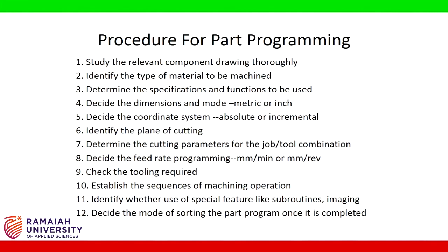Decide the feed rate programming, mm per minute or mm per revolution. Check the tooling required. Establish the sequences of machining operation. Identify whether to use special features like subroutines and imaging. Decide the mode of storing the part program once it is completed.